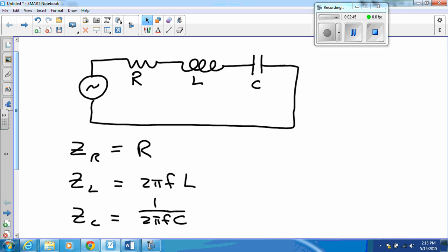When we were doing capacitors, you said they charge instantaneously. Is that just instantaneous to humans? Yes, that's the right way to think about it. We skipped the whole RC circuit thing, but had we done it, we would have discovered that when you have a circuit with a resistor and a capacitor in it, it takes a certain amount of time to charge up. That time depends upon the value of the capacitor; larger capacitors take longer to charge. It also depends upon the value of the resistor because in order to charge, you have to draw current.